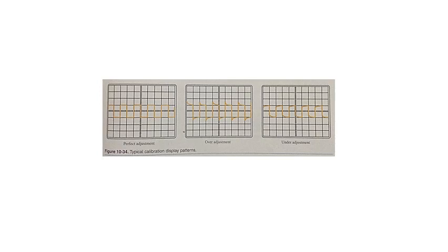A square wave pattern is generally placed on the screen to calibrate the amplitude and the time period. The square wave can also be used to correct any distortion caused by the oscilloscope's probe. First, locate a point on the face of the oscilloscope, usually marked Cal, which is the abbreviation for calibration. This point is where you will connect the tip of the probe.